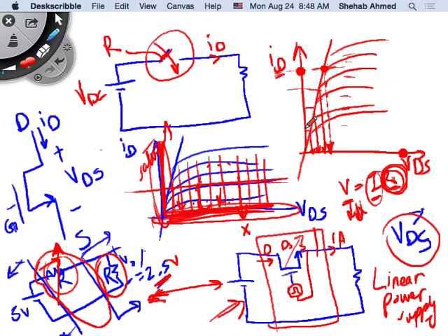Here, in power electronics, I don't do that. I don't operate here at all, where I end up having many values of resistance for the device. I only operate, let's say, along this line. When the device is on, I operate along this line. If I operate along this line only, then the relationship between voltage and current is what? It's linear, right? So it will always be the same value of resistance. If you decrease current, voltage will decrease. What does that mean? If this decreases and this decreases, then this can stay constant, right? And that's what happens.